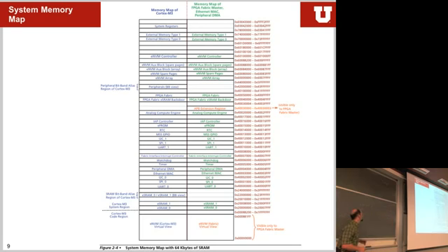And what happens is, if you want to clear one of these bits in this register, you write into this memory location and set the bits here. And then only the bits that you actually set in here will be cleared in here. So setting would mean you write a 1 in here, and then you make sure that this bit would, for example, be cleared. Or if you do it this way, so you set 0, 1, and the rest are zeros, then you would make sure that this bit will be cleared to 0 in the actual register. If you want to set a bit, you could use a second register. Whatever is set in here will then be set and applied to this register.